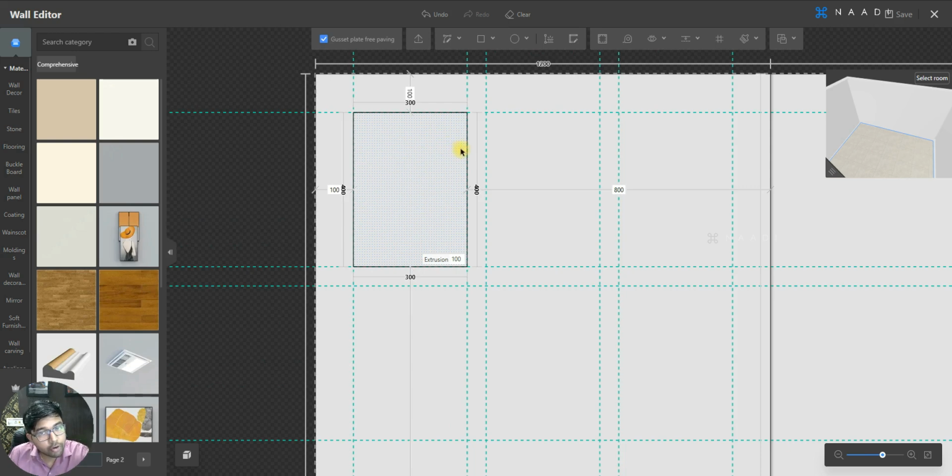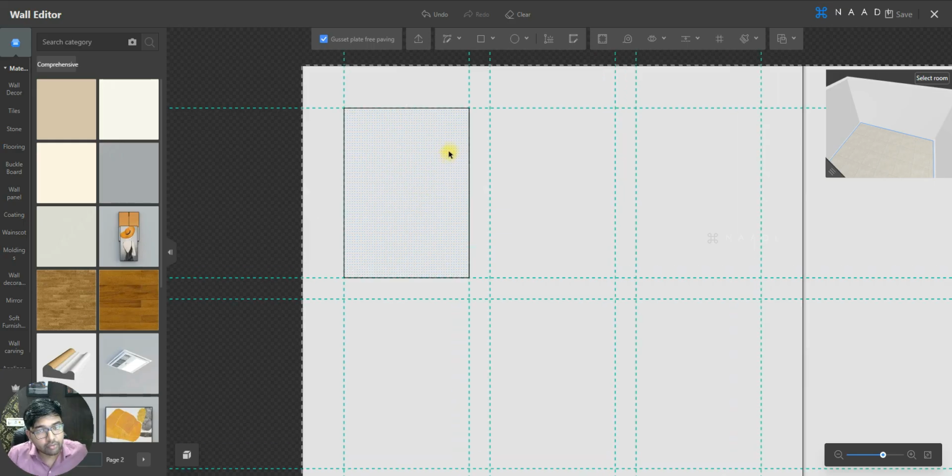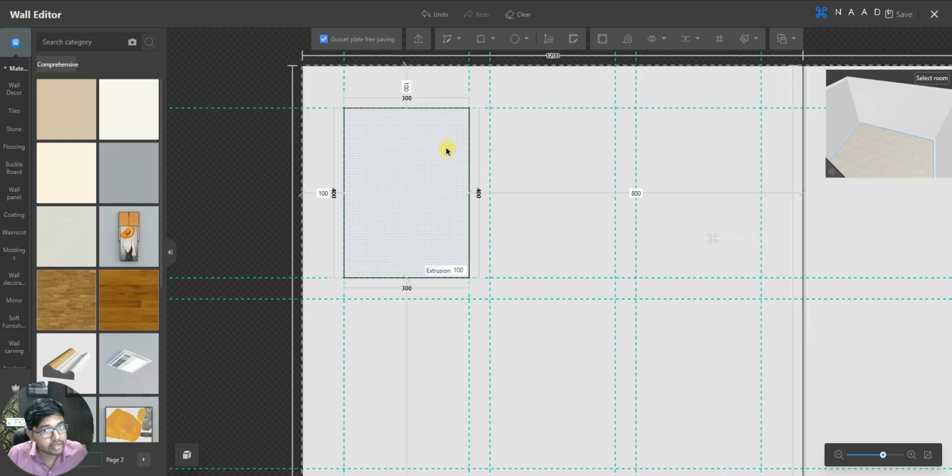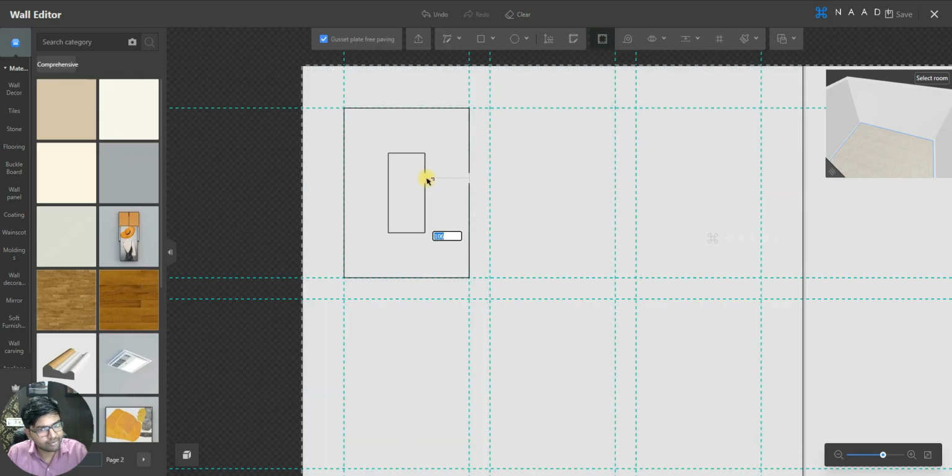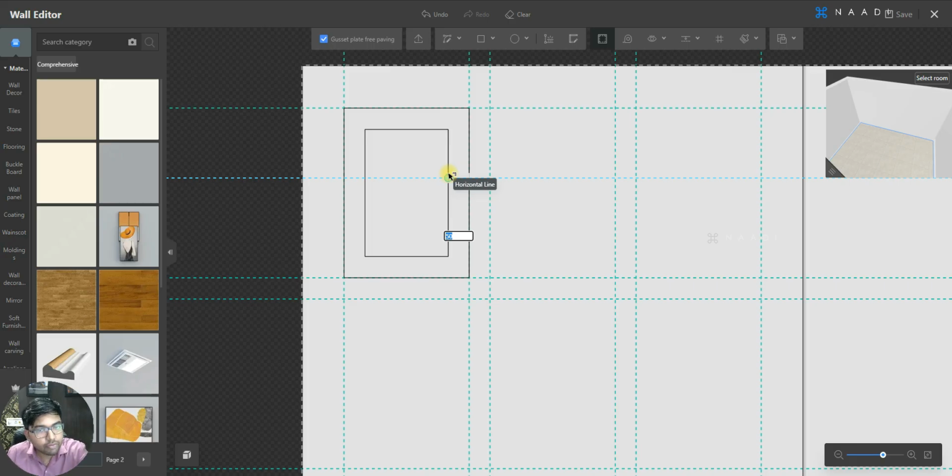I'm planning to go for a multi-level extrusion for this coffer. So for that I have to create another rectangle inside it with a clearance of 50 mm. For that I could use the offset tool, a shortcut with which I can precisely create an offset within the surface, and I can type in the offset distance. In this case I'm planning to go for a 50 mm offset.